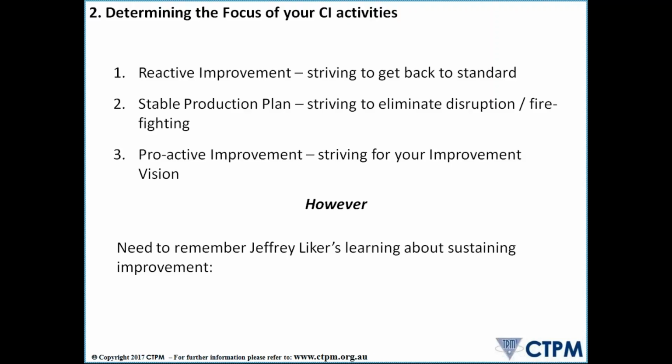I was at a site last week in Sydney, and again they're talking about how in one area they did a setup reduction Kaizen event, a very successful 3-day event at the time, and addressed a lot of issues to improve setups on their equipment. However, because that was the event, they walked away from it, and then they started doing some excellent work on one-piece flow in another area of the plant. Guess what happened to the area with the setup reduction? All went back to the old ways after about 6 months.